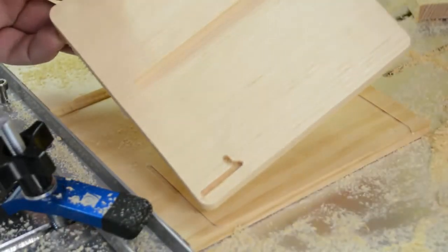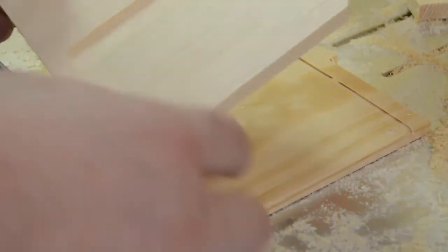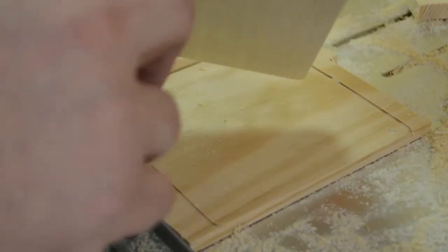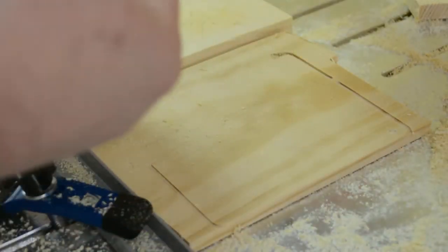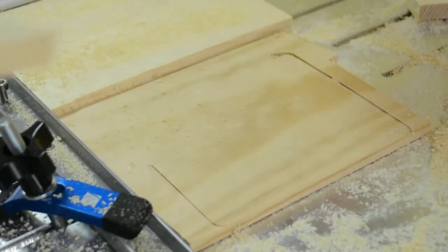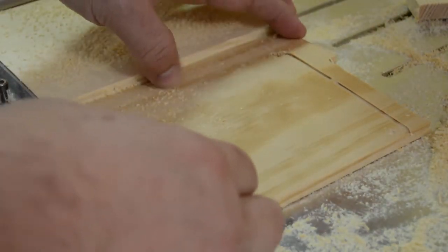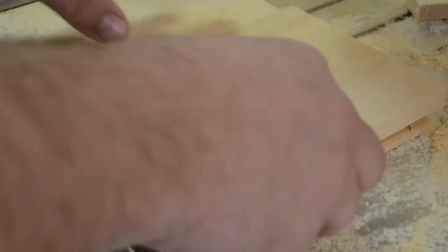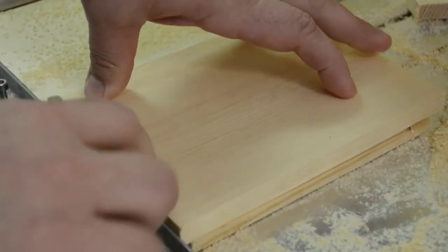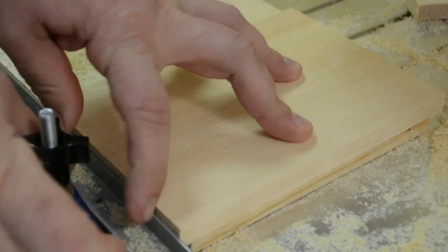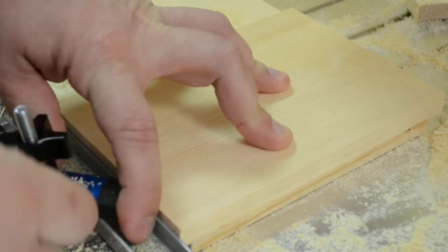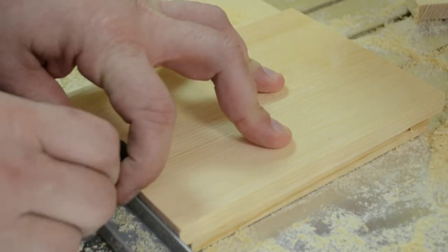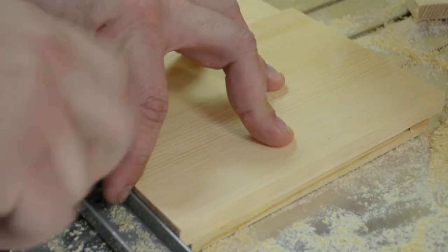And there you have it. There's the I all set with the number. It's all cut around. We broke the tabs off on both ends and we're all set. So now if we want to start the next letter, we just grab our next blank, place it right in the machine against the front guide, and we lock it back down with our clamps. And since we're lined up against two guides, we don't have to re-zero the machine.